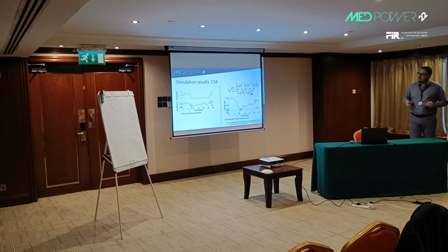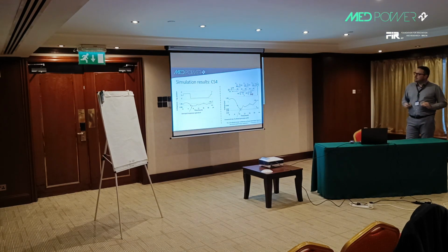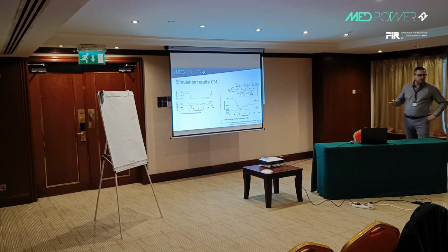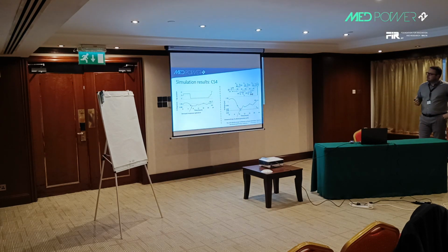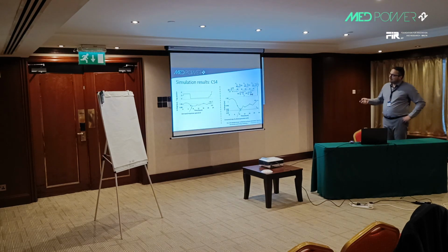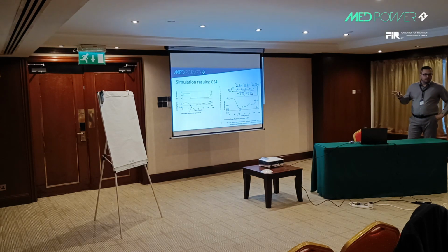We see that the voltages at some buses drop lower than 0.9 per unit. But we also see that the voltage at bus 5 drops below 0.88, which is the undervoltage threshold for the voltage protection of this unit. Therefore, the unit connected to this bus is also disconnected due to the undervoltage protection.